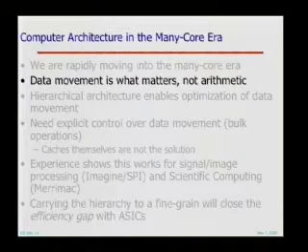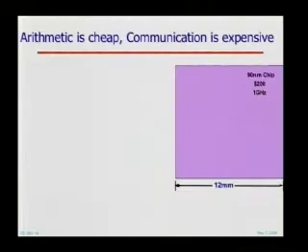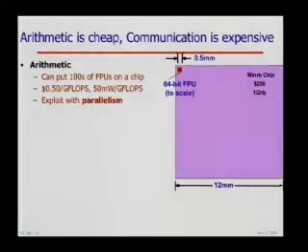Now let's look at sort of what type of architectures the technology today is driving us to. So what is the canvas that we get to paint on as computer architects? So here it is, probably slightly obsolete, 90 nanometers. I should update this slide to 65. But if you have a 90 nanometer chip, say 12 millimeters on a side, which is kind of a friendly size for manufacturing. By the way, the hero microprocessors are like 18. And you can actually manufacture this for well under $200 in quantity. This is how big a 64-bit floating point unit is. This is to scale. Arithmetic is really inexpensive.